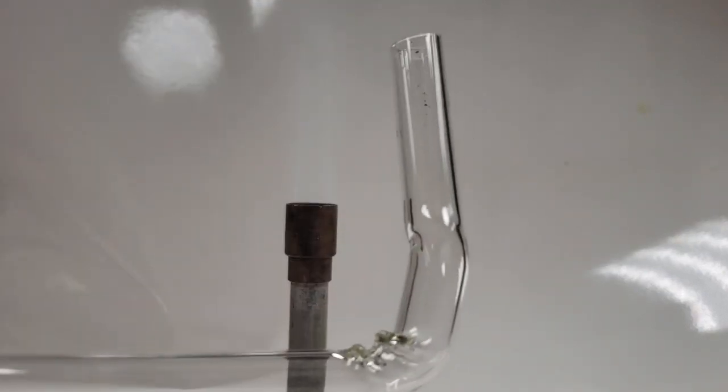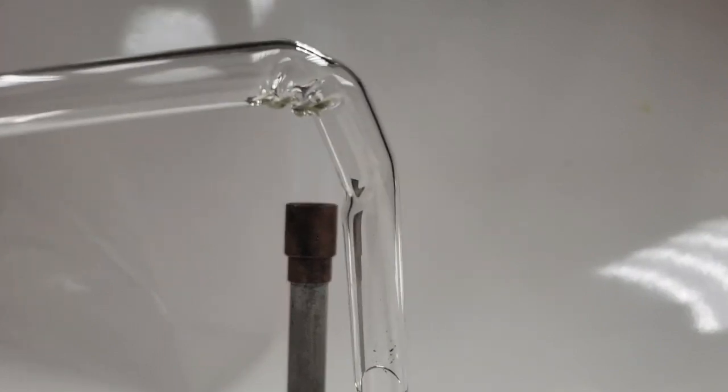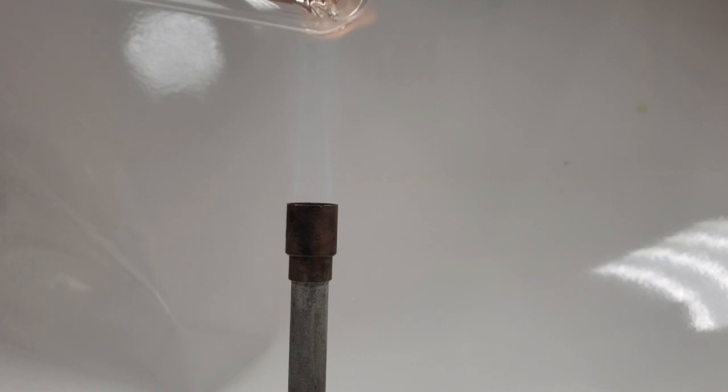All right, so you can see I've got a bend there, and it's not pretty, but it will work just beautifully. Now, if I just cool this right now, it will crack. I need to do what's called annealing. So I'm just going to gently heat it over the top of the flame and cool it off by slowly moving it farther and farther away from the flame. I'm not going to show you that on video, though. It's really boring.